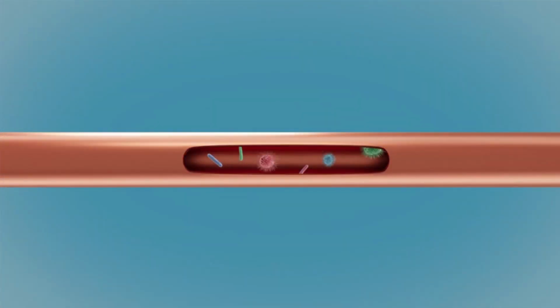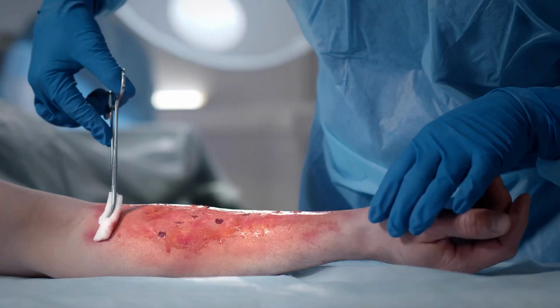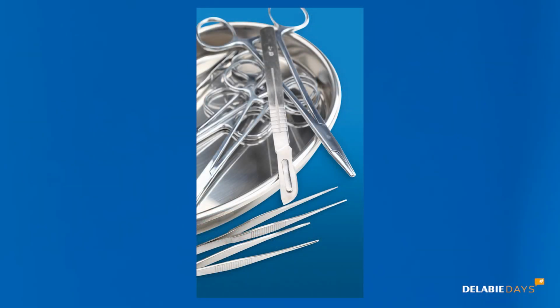If it's not monitored and controlled, bacterial development in the water system can become very problematic. The water quality is at risk of deteriorating, not only chemically, but also at a microbiological level. Waterborne pathogens such as Legionella pneumophila and Pseudomonas aeruginosa will develop. These opportunistic pathogens will then proliferate right inside the biofilm and the amoebae in the water distribution system. They attack immunosuppressed patients in different ways. Orally, for example, or by inhalation for Legionella, when a person is taking a shower, or for Pseudomonas aeruginosa, by direct contact between contaminated water and open wounds or burns, or with a medical instrument that has been contaminated by water from the system.